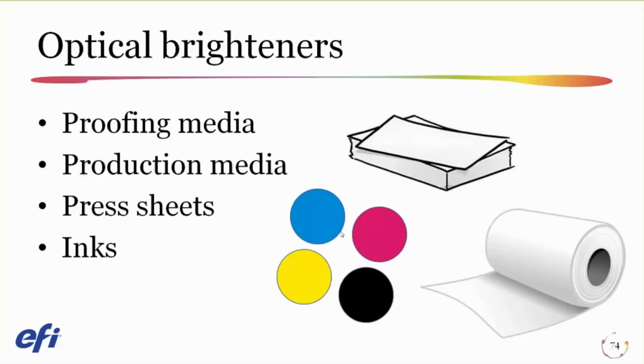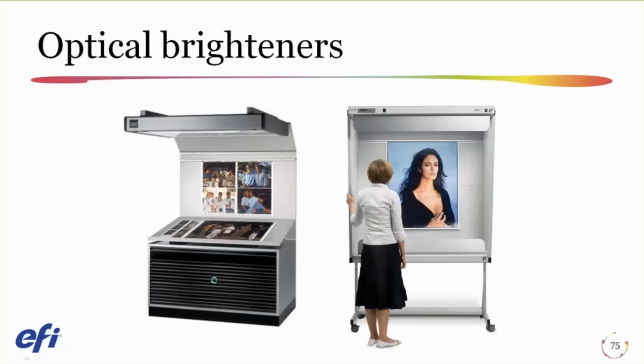And inks, especially yellow, can have a different amount of UV brighteners than some of the other inks. Well, now there's something that's going to cause problems. Yellow ink on top of other inks, or not on top of other inks, looks brighter and can do a masking job on the media, and let's face it, cause problems. The best would be to get media without optical brighteners, but then your costs are going to go up.